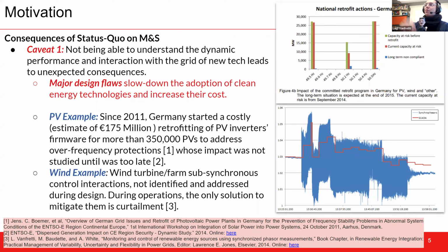So this was about 13 hertz, this one. And of course, that was kind of visible through flicker. Now the problem is, to get rid of it, you have to ramp down the wind turbine. And if you ramp down the wind turbine, there's only our great friend gas or coal. Well, only gas really that can speed up to catch up to that. So it will create more operational costs if you want to get rid of these nasty resonances.